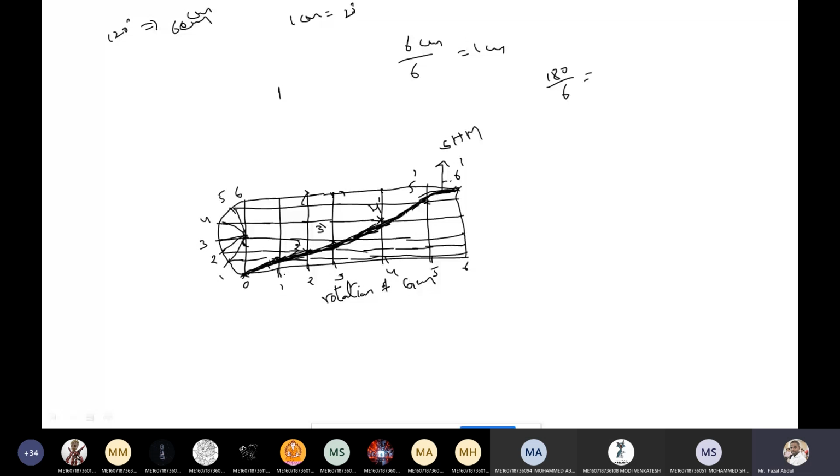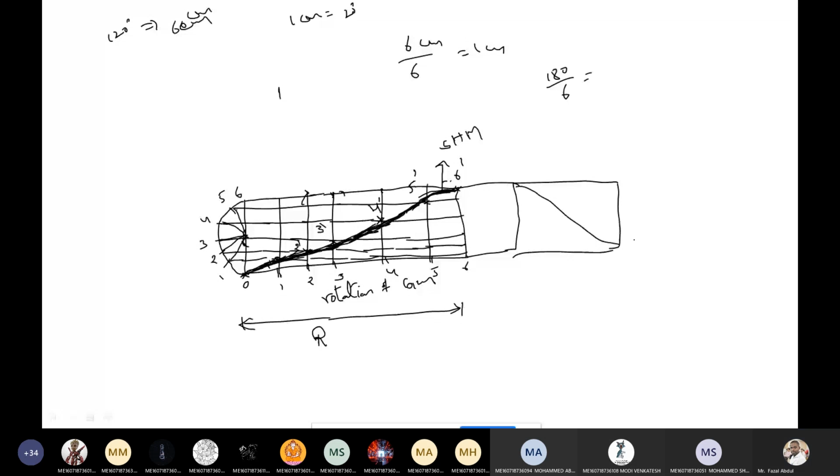Now the period from 0 to 6 is known as the rising period. In the same manner, we need to construct another diagram here. After rising, the follower has a rest position, that is dwell. After the dwell, the follower is going to fall down, and after falling, the follower again has a dwell period.